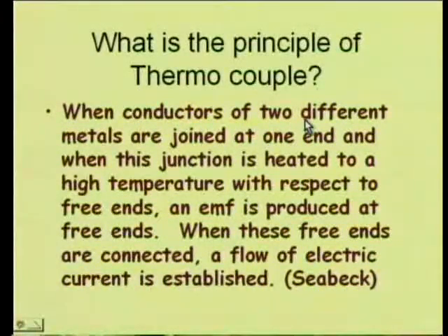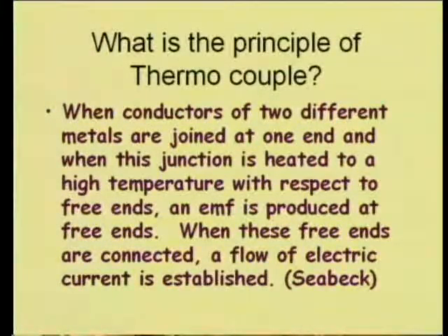Let me explain this. When we take two wires of different materials, and they are joined either by brazing, welding, soldering, or even simply twisting, then when these two are connected at one particular joint and we heat it to a high temperature, what happens? EMF is generated at the free ends.